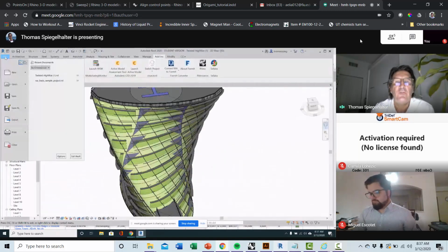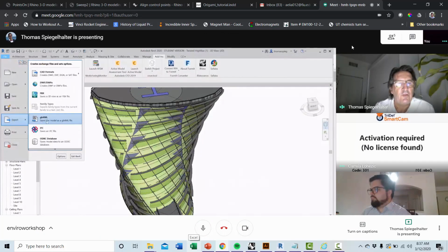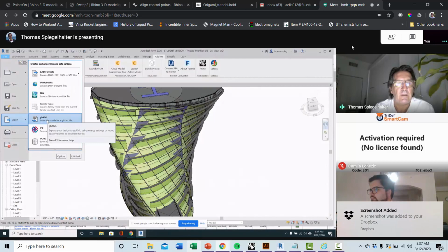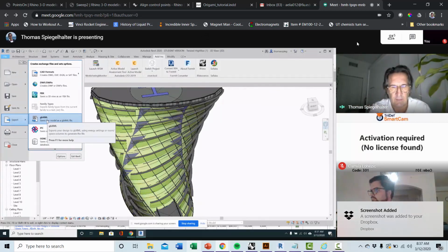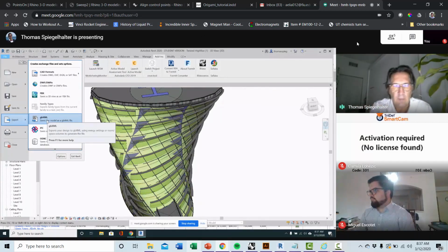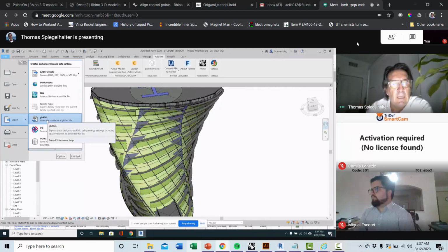So you go to, do you see the Revit file? Albert and Camilla? Yeah, you go to export and then you choose GBXML file, and you would export the Revit file as a GBXML file and then re-import into GBS. Now that workflow, we have an extra tutorial for that, and we will provide that to all of you. It's already posted on some Canvas Studio modules.